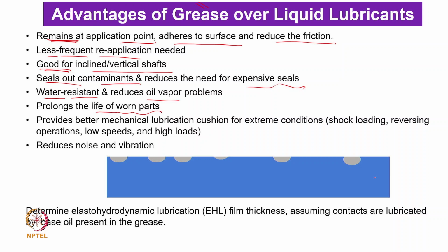That has been shown. Now suppose this is a worn part, I'm using a worn part, and this is a pit. Now if I operate this with a grease lubricant, grease will fill these pits, and it will give a cushioning effect. That's what we say, it will give a cushioning effect.